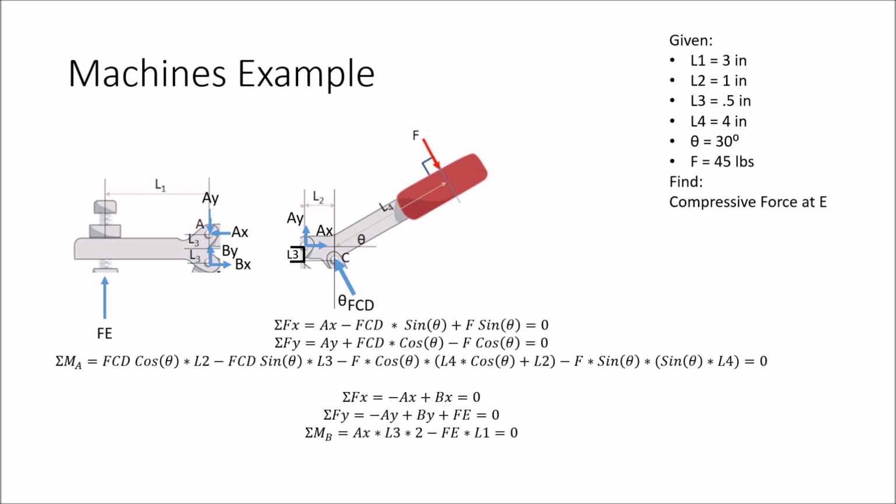I am going to be thorough, however, and solve for all the reactions, which can be found after taking moments and summing forces in the X and Y direction. And here we have our final force at E, our compressive force of 51.7 pounds.